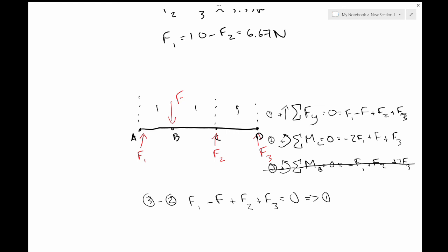A lot of the ways that we get around that on the team is by making worst-case assumptions. If this load F is going to be distributed as F1, F2, F3, and we can't determine what they are, we might make the worst-case decision. Let's say that F1 equals F2 equals F3 equals F, which is obviously not realistic. But if having each of these forces being big is bad, then by overestimating them, we know that we're going to be on the safe side when we're designing components.